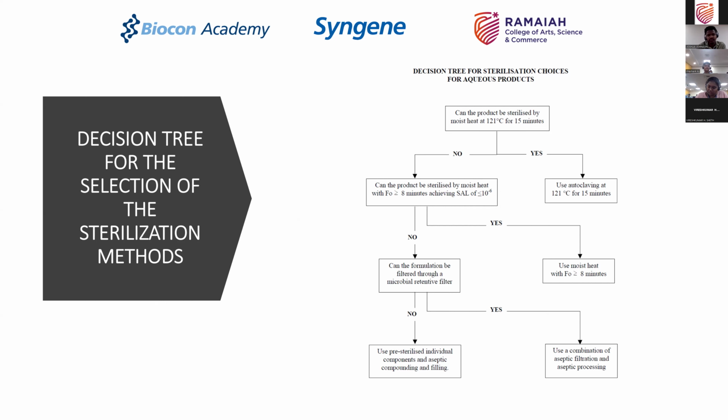Okay, so if the FO value is greater than or equal to 8 minutes and you are achieving a sterility assurance level of 10 to the power of minus 6, by changing the condition of moist heat, if you are able to achieve the sterilization of the product, then use that as a technique. So again, that would be a technique whereby you will still use a terminal sterilization at a different condition.